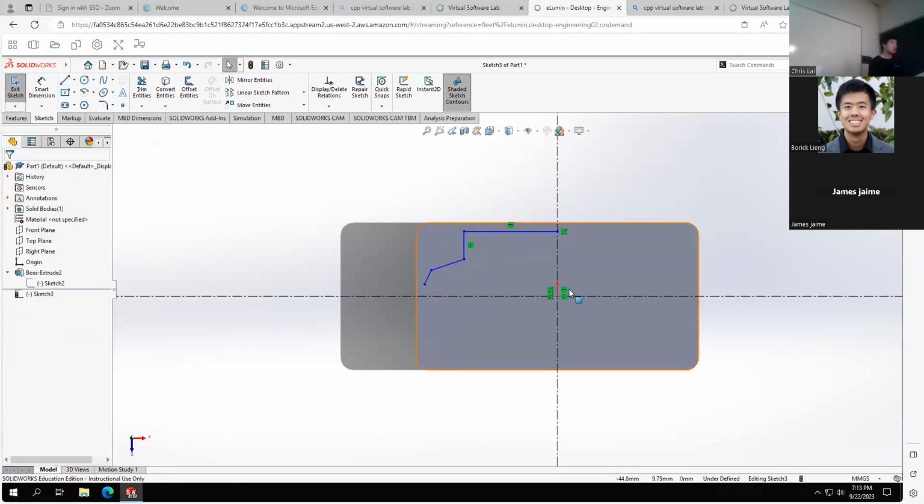Okay, so you don't have to have everything exact all the way, right? I know that my sketch is going to be completely symmetric, left and right, and up and down. I apologize, it's not the right vocabulary, but you don't have to have everything already set. You could always play with the constraints, so if you mess up, you will have a way to fix it by placing constraints.